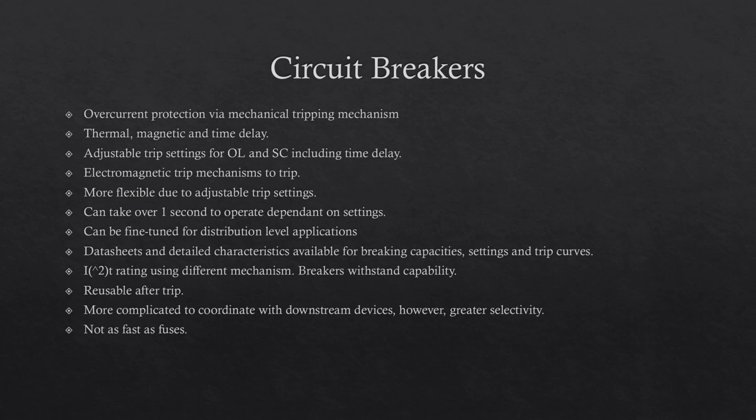Again, data sheets are available. You can come with different settings already pre-programmed. They're quite easy to set up as well. Some of them, literally, you go to the front of the circuit breaker, you use the trip unit, and you just set whatever you want your trip, what I like to call plug setting, in relation to your CTs. They are reusable after a trip,